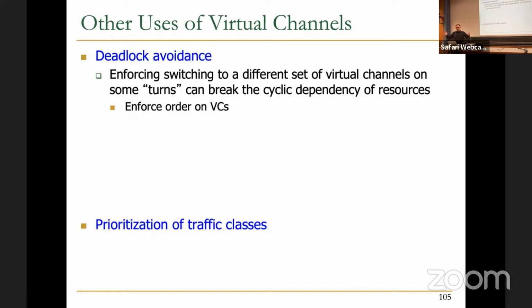At the first hop, I have all the virtual channels available. After one hop, one virtual channel is no longer available to me. After the second hop, another virtual channel is not available. So you're reducing the number of virtual channels as you go through the network. If you want an analogy, you don't make a circle, you make such a shape. So it's not until you get to the destination. It's very similar to that.